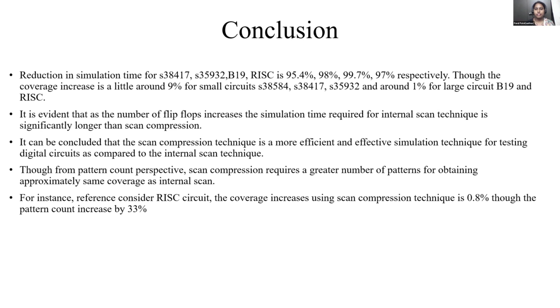And for internal scan and compression, memory flops are not put in the chain, because a memory is a sequence of a lot of flip-flops. So instead of reducing our area overhead, it will increase area overhead and increase time to test. So it will make it worse rather than better. So we don't test memory under scan.